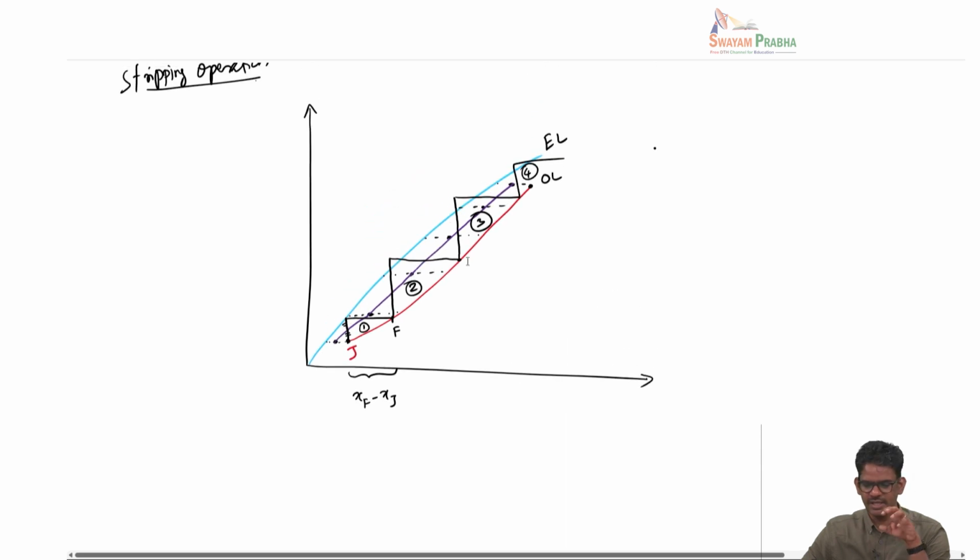So here you should know how to get the equilibrium line, which you know from Raoult's law, Henry's law, etc. You know how to draw the operating line based on the mole balance equation, and once you know that, you can do a simple step construction like this to get the NTOG or NTOL. Then calculating HTOG, HTOL is straightforward; multiply these two and you will get the total height of the column. Okay, we'll stop here.